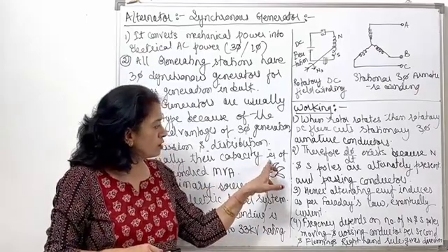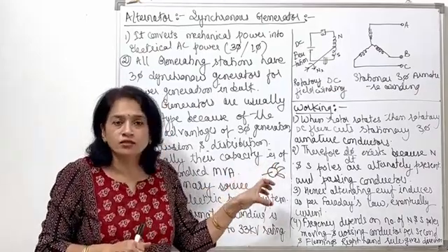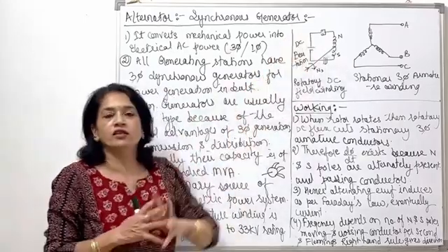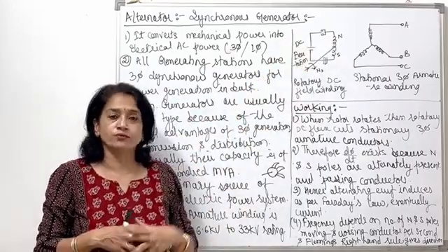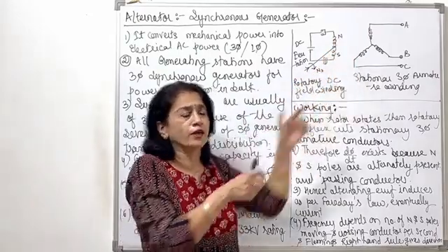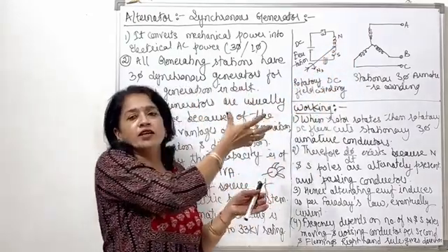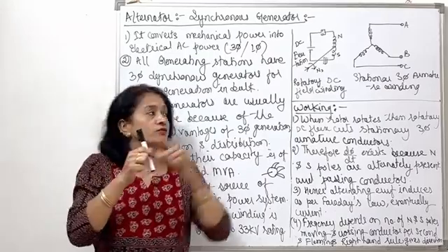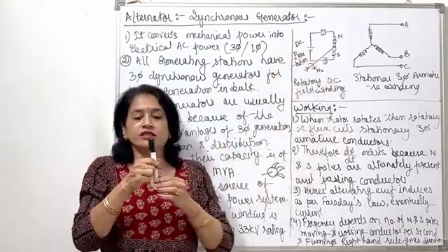So as soon as the water pressure or steam pressure turns the turbine, the rotor turns, and once we give the DC supply across the rotor winding, it produces north and south poles, and at the same time we are turning it. So what is happening? A DC field exists there because of the DC current supplied by the DC excitation.